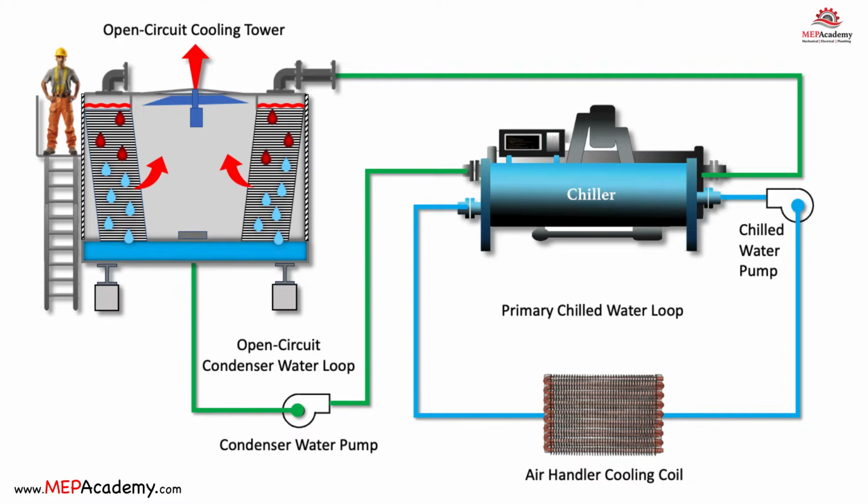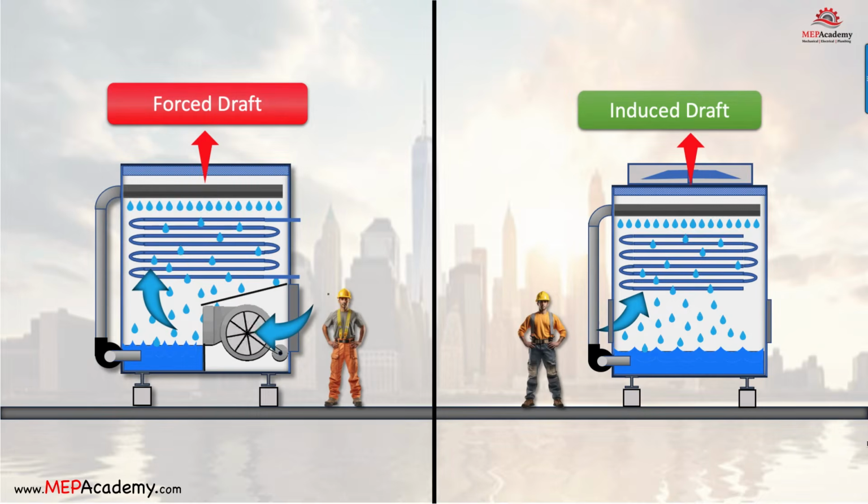The water in the basin is then returned to the facility or the condenser side of a water-cooled chiller, which could foul the chiller's condenser coil if the water is not properly treated. The makeup water to the tower can also introduce contaminants to the process water.